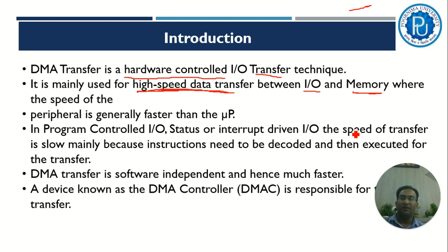So DMA transfer is software independent, and hence much faster in comparison to the other input output transfer techniques. Here a device known as the DMA controller, direct memory access controller, in short called DMAC, is responsible for the data transfer.